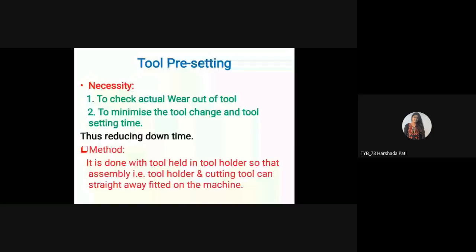So you just take care in terms of the tool setting, then to minimize the tool change and tool setting time, you just ensure that once you install that tool into the system, you set up that tool. Whatever the operation time for that particular tool, the setting time for that tool, and ultimately the time for the tool change, you have to do this calculation before the manufacturing.